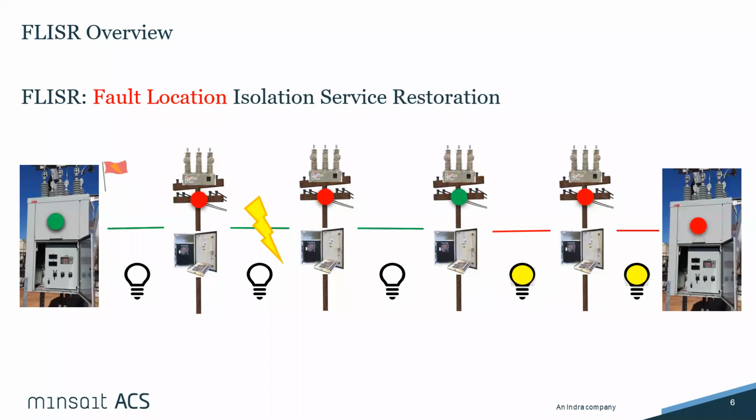So obviously the breaker that cleared the fault certainly also saw the fault, so its fault flag is up. And then all the devices downstream, while they may not have the capability of actually clearing the fault, can certainly see the fault, and they would raise their fault flag saying they saw it. Now, this would be the last device that actually saw the fault, because it's the last one upstream of the actual fault. So we therefore know that the fault is somewhere in this segment.